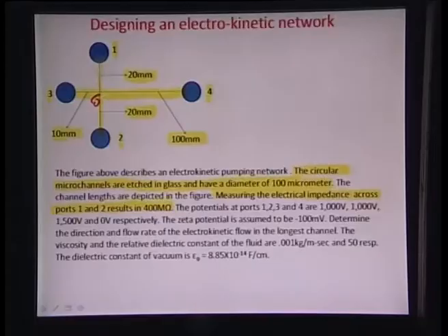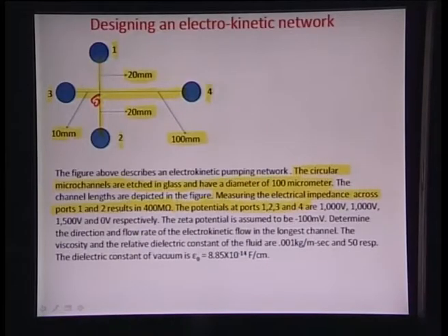We assume that in microflow domains continuum mechanics still holds, and there is flow continuity. Okay. And so in this case we presume that the resistance per unit length is constant. So the potentials that we apply for driving the flow have to be applied perpendicular to the cross sectional area of the microchannels containing these fluids.